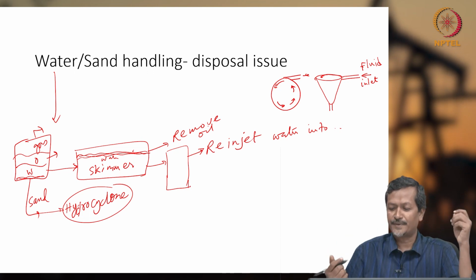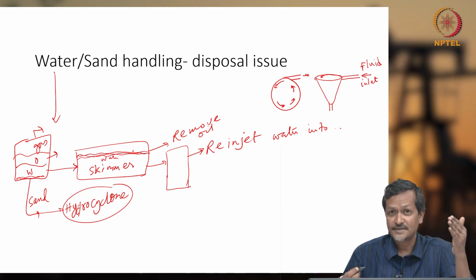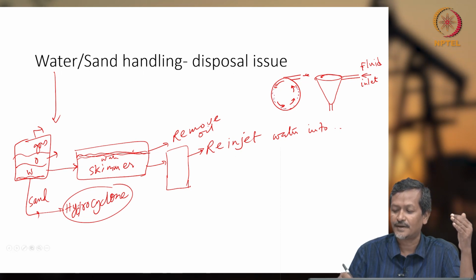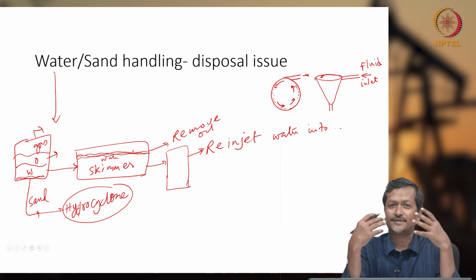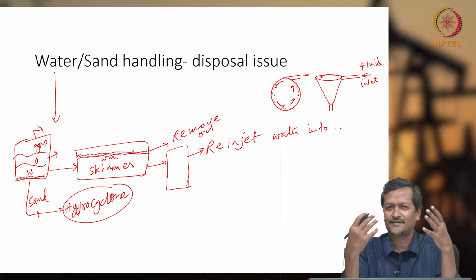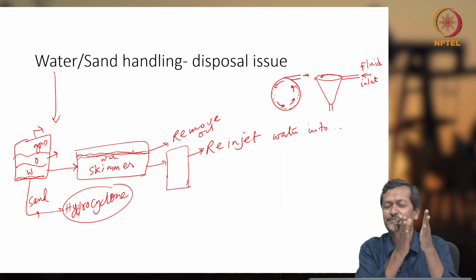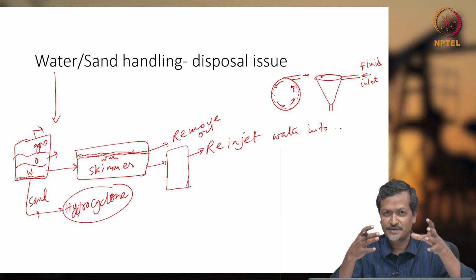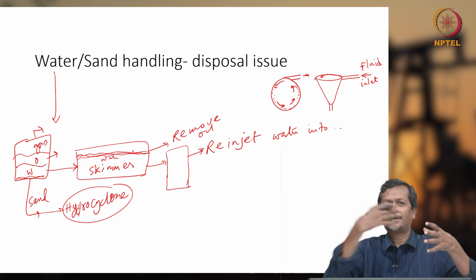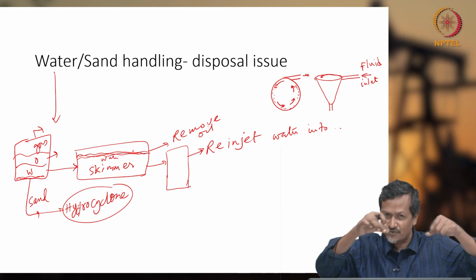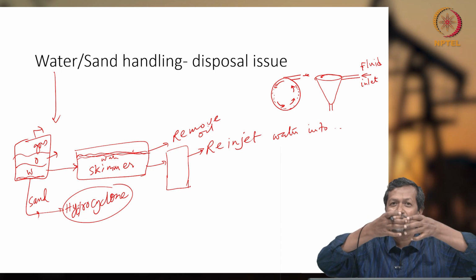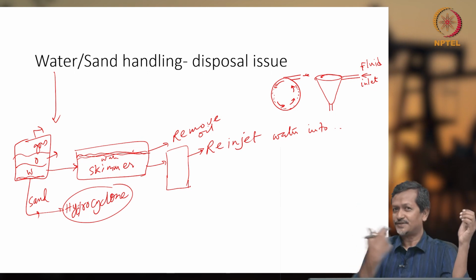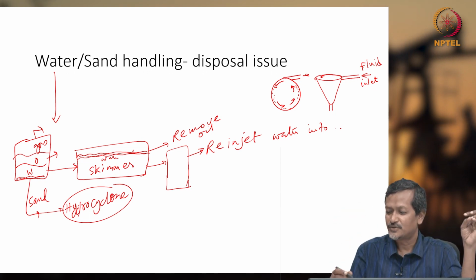What is happening is, because of centrifugal action, high density particles will try to touch the wall, and low density particles are not capable of pushing the high density particles. So what will they do? They will keep rotating in the center, but the high density particles, with very much energy, will be rotating and taking the space of the outer area. The inner core will be low density particles. High density means sand. So high density particles will be rotating at a larger radius and rotating down.